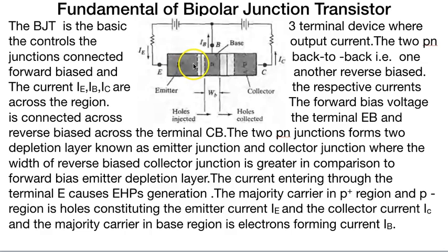Here they have large velocity that helps them cross this thin depletion region, and we already know from our previous lectures that the minority carriers are unaffected by the width of the depletion region. So they don't require much energy to cross the collector-base depletion region, and hence they can be transferred to the collector region and complete their loop.